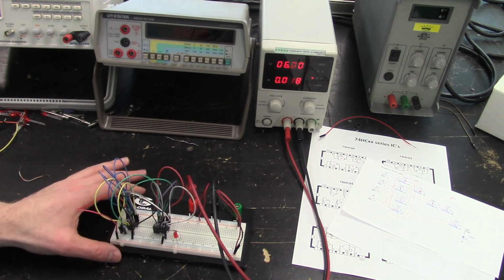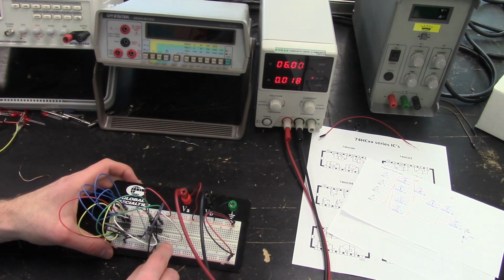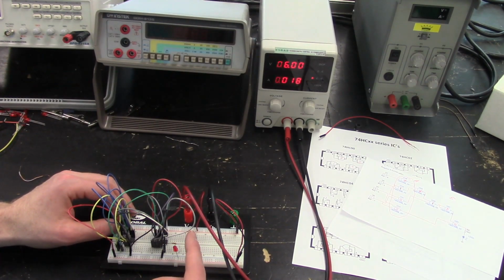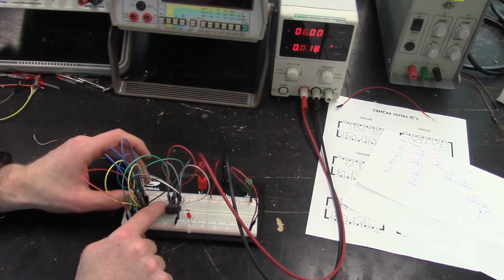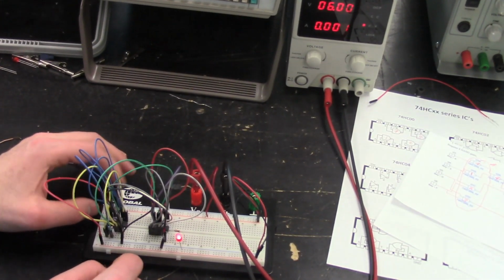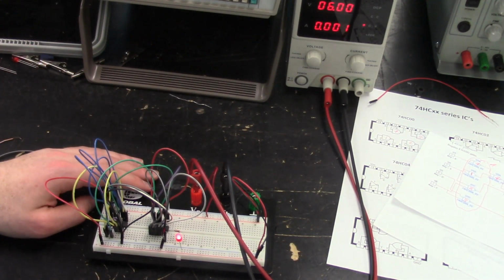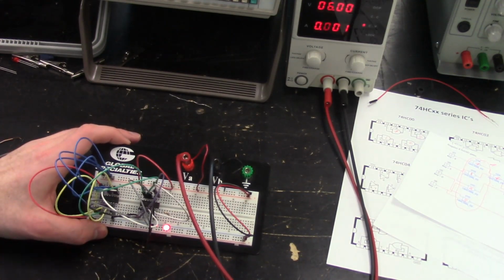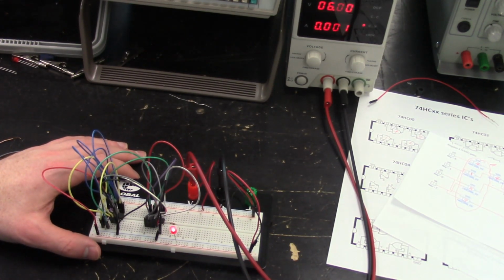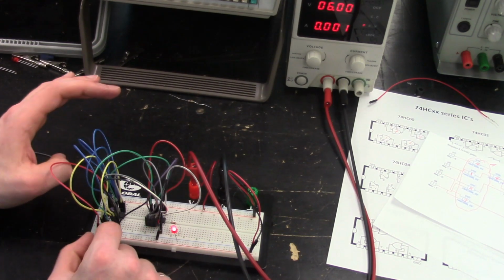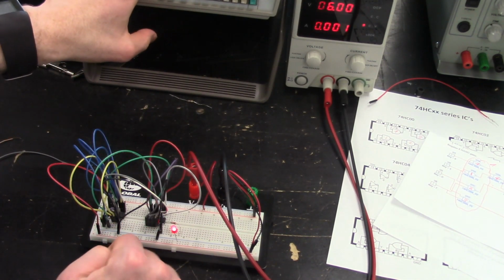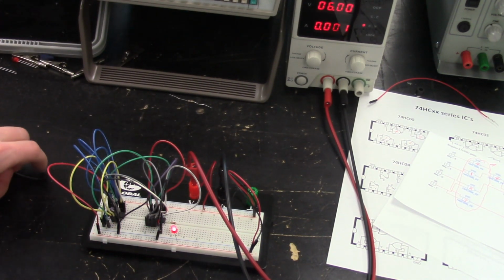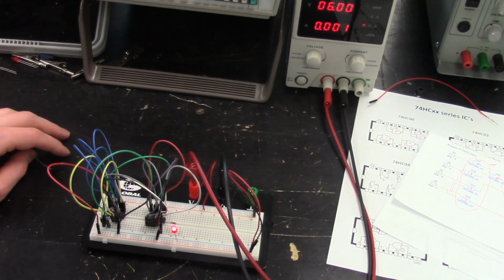So another thing that we could have done while debugging, if we hadn't seen that light go on for a moment, to check if things were actually hooked up across the boards here, is mess around with the inputs and see if that's giving us a different result on the current. Other tricks that we could do if things still weren't working after we checked all the wires would be to hook up the multimeter and double check that voltages in different spots are what we think they should be. And that's basically what you do.